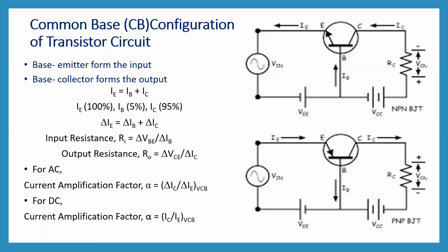We were discussing the configuration of transistors, and in the last class we have seen common base configuration, which means the base of a transistor is common to both the collector and emitter. So today we will discuss the other configurations and how we can use the transistor as an amplifier and as a switch. So in common base, you have seen that this is the input.